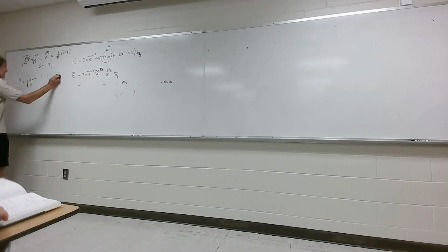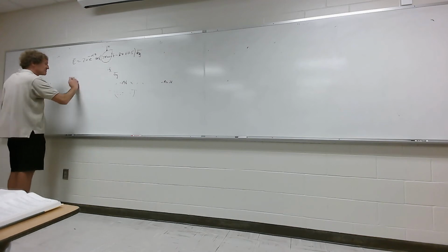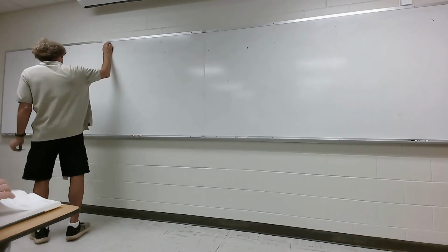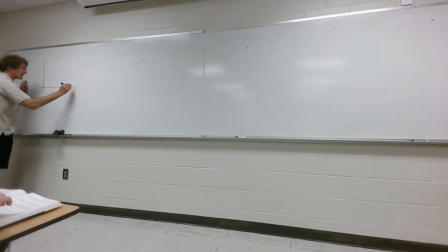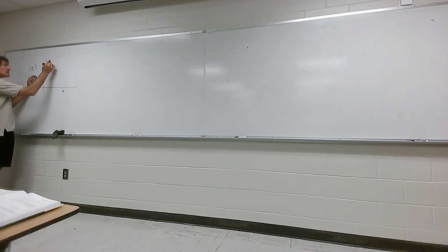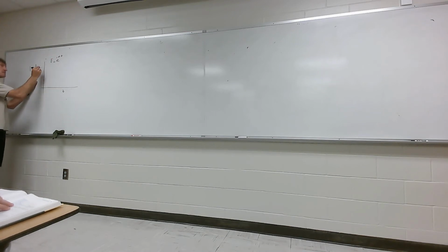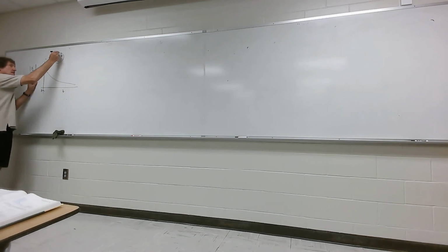I want to talk about, first, we talked about propagation in good conductors, and I just briefly alluded to skin depth. Do you all remember that class? So I said that in general, if we have an electric field in a pretty good conductor, we get this kind of behavior versus depth. If I take the magnitude of the E field on this axis, the value would be equal to E naught e to the minus alpha z. We forget the phase because we're talking about magnitude. So at z equals 0, it's E naught, and it steadily goes down at an exponential rate.